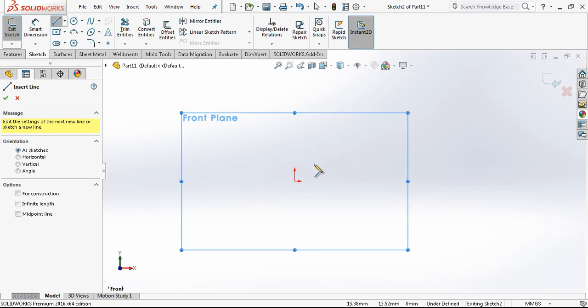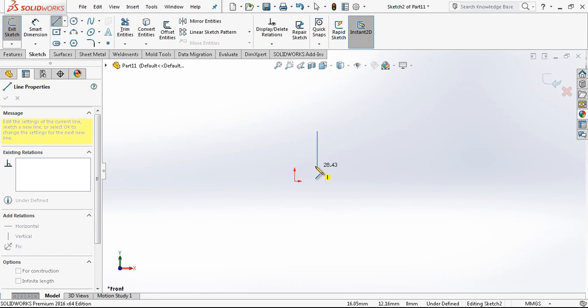In SolidWorks, before you start to work, you should think about your sketch, where it should be, like in the middle of your origin or in the corner. This is so important. As you see in the screen down below, you are seeing your dimensions, so how far you are from the origin, and that's important. SolidWorks wants to know exactly where you are according to the origin. You should define it, and that's going to allow you to have fully defined sketches.